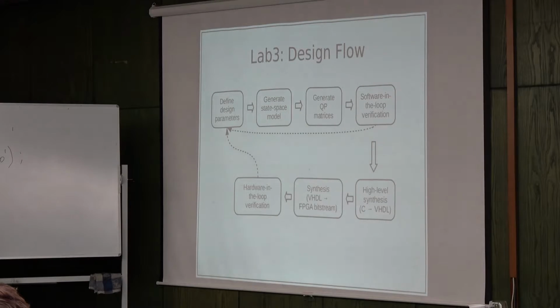These steps can be automated, and the automation happens with the ProType software tool that we have developed in our lab. The main idea is that you give C code to the tool, and ProType takes that C code and automatically converts it from C to VHDL using Vivado HLS on the underlying levels, then automatically converts VHDL code to bitstream. Again, you just have to call one MATLAB function instead of creating the project and doing things manually.